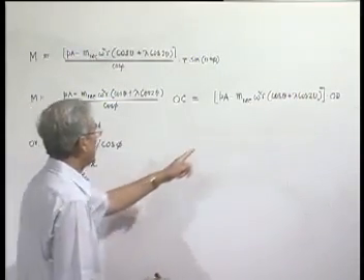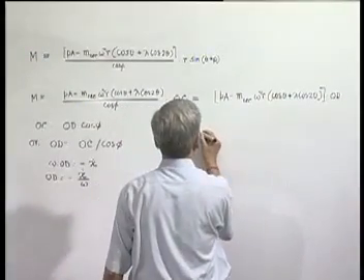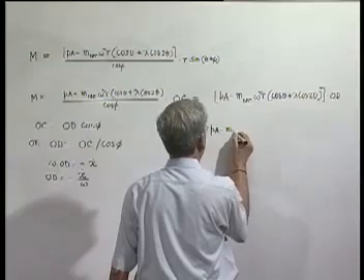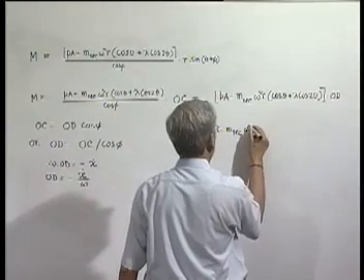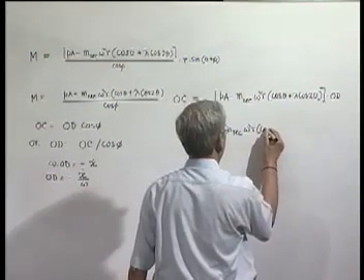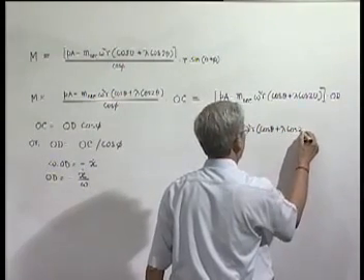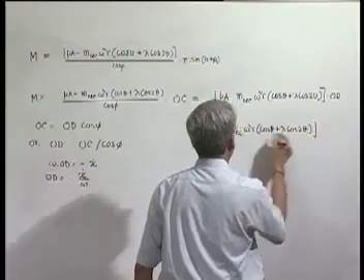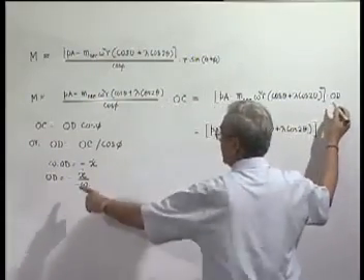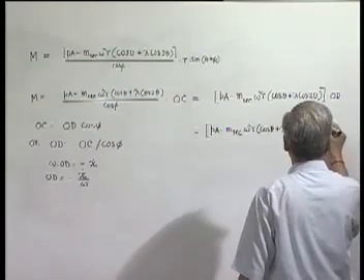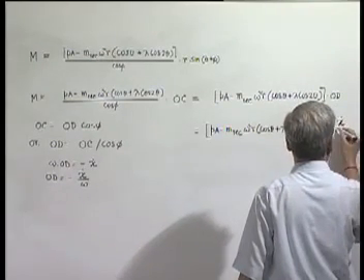So using this here again, we can therefore write this is equal to PA minus m reciprocating omega square r cosine theta plus lambda cosine 2 theta, and OD will be equal to minus x dot by omega.